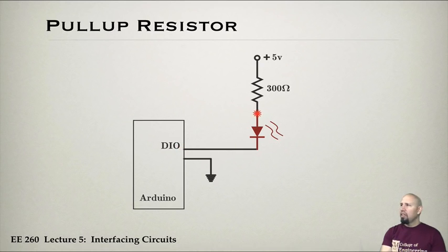And so basically that means I'm not getting any voltage drop across this device. When this goes to 0, then this becomes 0, and then current flows. So it's very common to use pull-up resistors. We'll see them all over the place. Remember, the outside world is still analog, and so that's why we have to throw in resistors and stuff like that. Sometimes we'll throw in capacitors and other things because they're important.